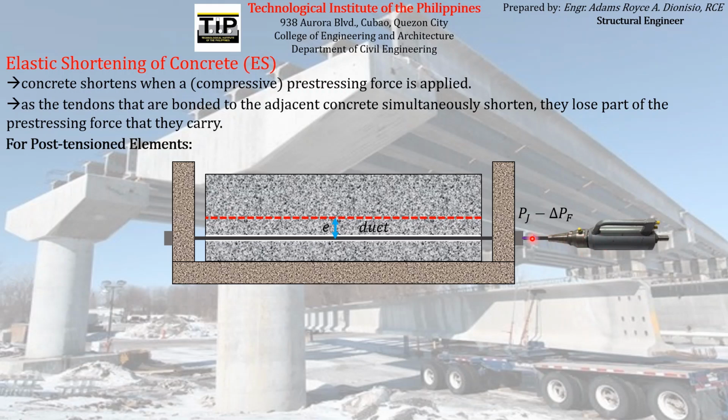by the hydraulic jack. But in the case of post-tension, we know that the pre-stressing reinforcement tends to have friction with respect to the duct or the sheet that covers it. The tendency is that the magnitude of the jacking force applied by the hydraulic jack loses some of its magnitude because of the friction between the pre-stressing reinforcement and the duct or sheeting that covers it.